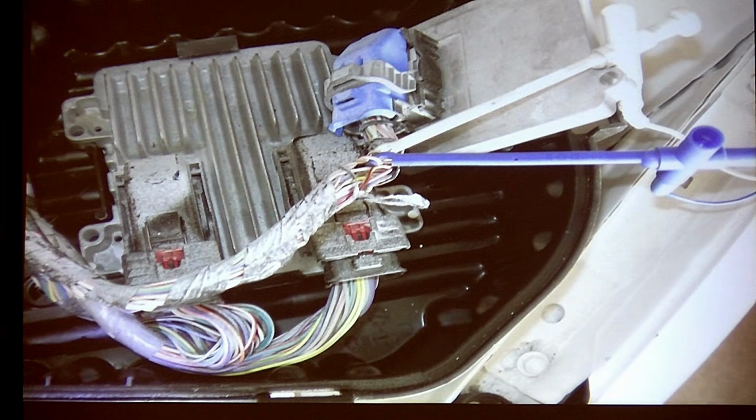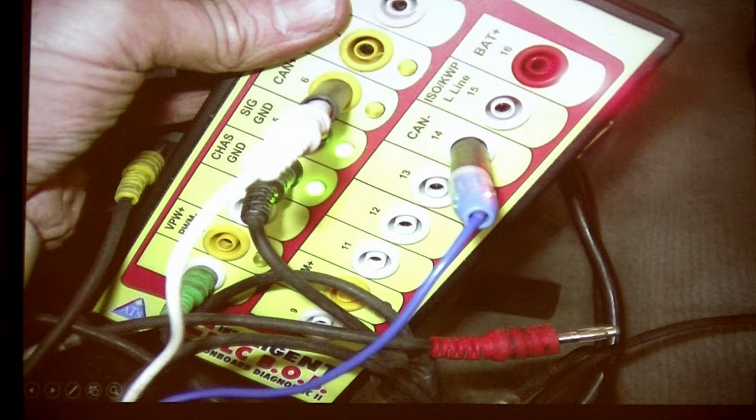I want to play a game. I want to show you guys something. I'm going to go back out on the TCM because that's where I am with these two wires. This is the 2 CAN, and I'm going to go into the car. Do you see how on my bridge I've put them right into pin 6 and 14, CAN high and CAN low? Now I'm plugged into my scan tool. Can I talk to that car?